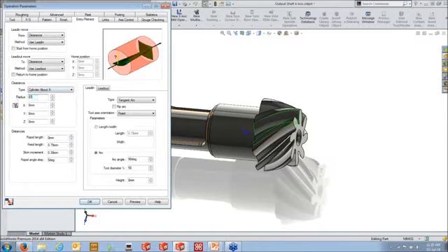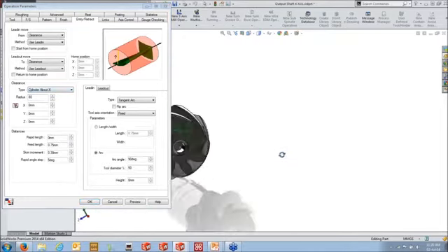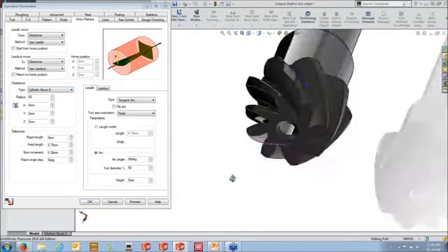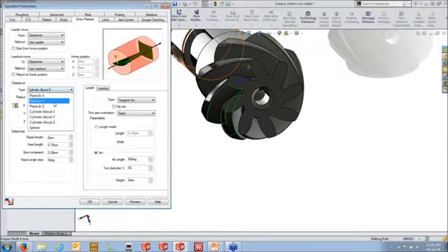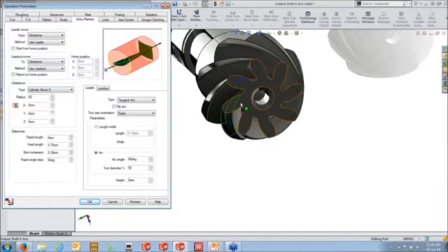And we'll set up our radius value here for the actual clearance plane. Now by doing this, if for instance my toolpath finishes down, say, here, what it's going to do is it's actually going to do a radial move away to the clearance plane and then retract up. If we, say, use plane in X or plane in Z, for instance, then what happens is it might just retract straight through our part. So by using the cylinder about X, it will actually do a radial move first to make sure it can clear that distance and then retract up.